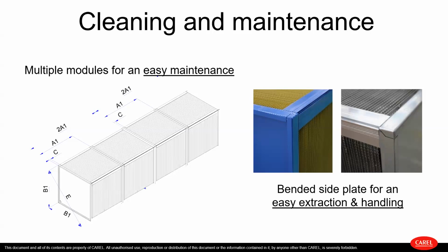the plate heat exchanger. But this plate heat exchanger can be delivered in pieces, in slices, let's say, in order to support you in the best way for the maintenance. You have small pieces to handle, small pieces to clean, and also to put inside. They are lighter, which means faster maintenance. Maintenance can be done easily with water or compressed air inside the heat exchanger.